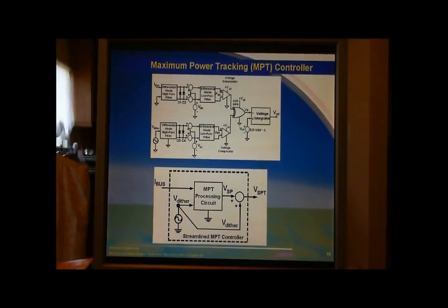When the voltage at the output of the exclusive OR gate Vx is at a DC average of around 1/2 of the bias power supply, or 1/2 VDD, it will cause the voltage integrator to stop integration.